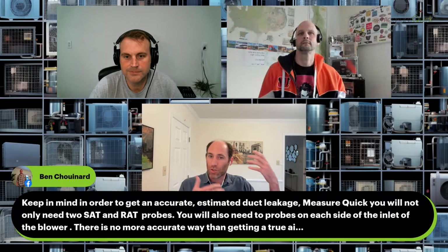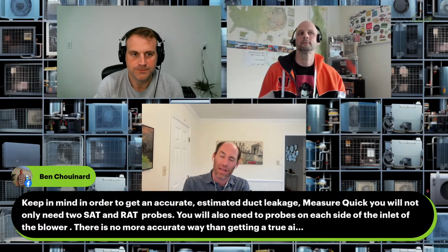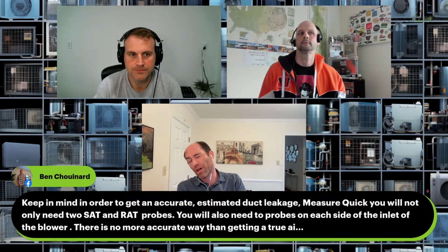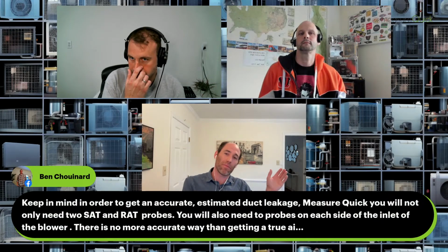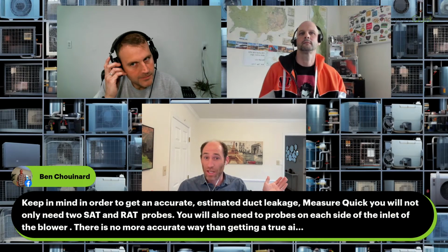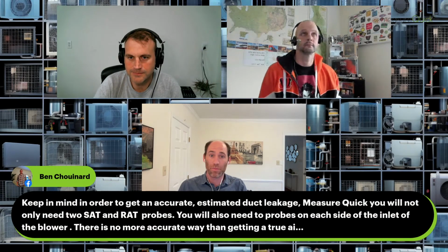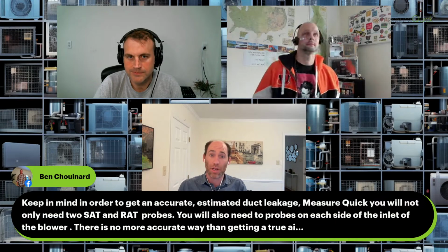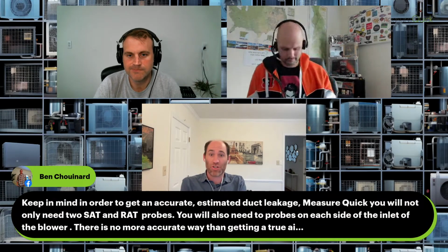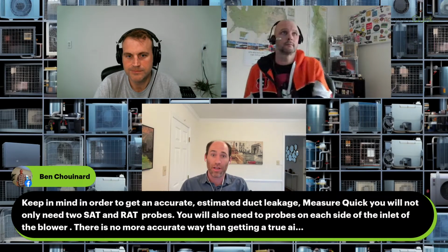And then they have to do some calculations to be like, well, I slowed it down by measuring it, but I probably only slowed it down by this much, so it was probably that much. Well, with a lot of these, you end up with plus or minus 15, 20% error. That's why some people call them random number generators, because you can measure a flow, measure it again, and be 25% off from the measurement you just took.